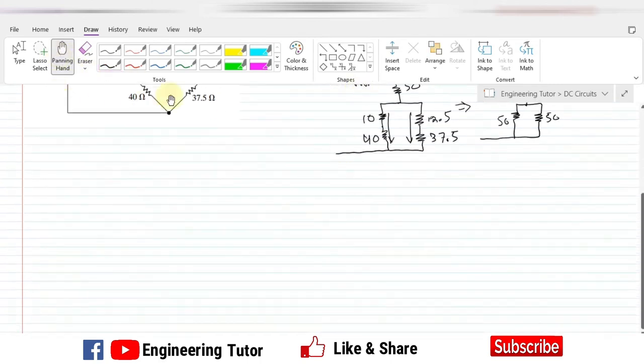Let me go down here and solve it. Now we can see that this circuit has become this, and the equivalent of the two 50 ohm resistors is 1 over R equals 1 over 50 plus 1 over 50, as the two resistors are in parallel.